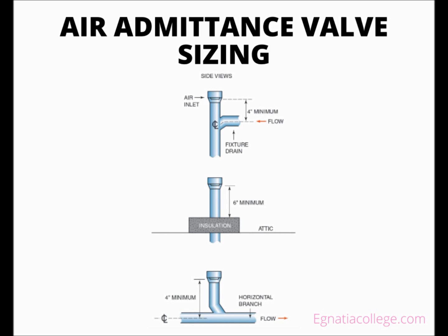An AAV cannot be installed in supply or return HVAC air plenums or be used in certain specialty DWV systems such as acid neutralization systems. Access must be provided to replace an AAV. Wall boxes with louvered access covers are sold for this purpose.